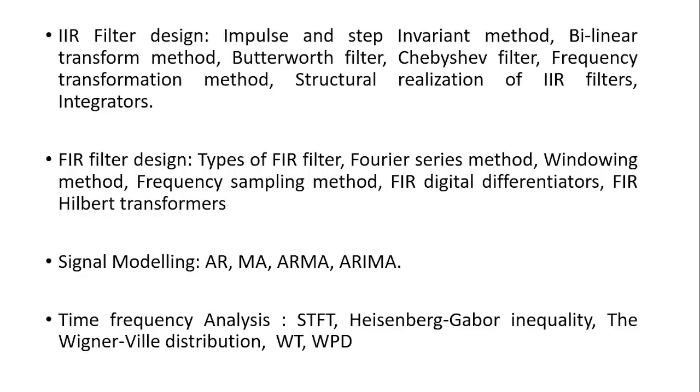So similarly in filters also, when you give an impulse input, either the response will be for a prolonged period of time, or it will come down very quickly. If the response comes down very quickly, then it is called an FIR filter, and if the output response is for a prolonged period of time, then it is called an IIR filter. So we will be discussing the different types of filters over here, and how to design those filters.